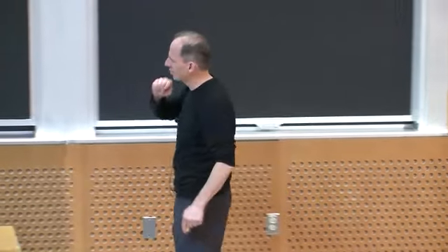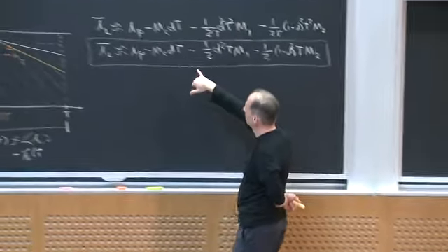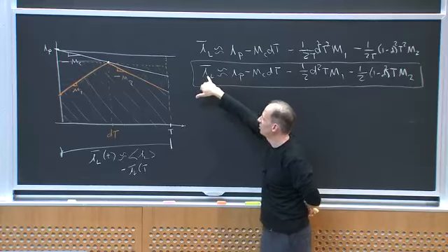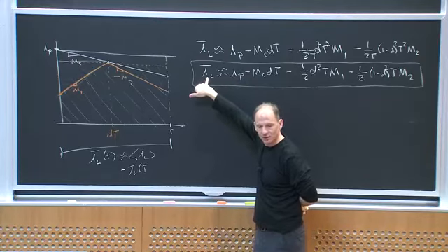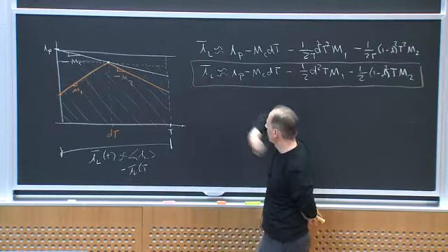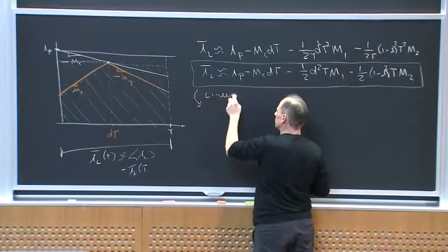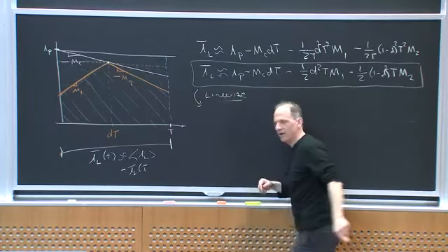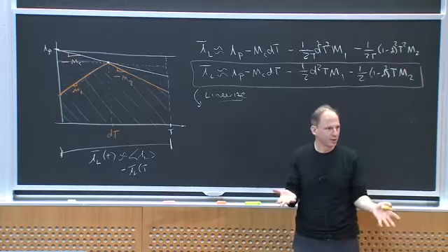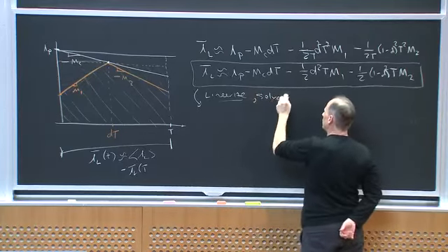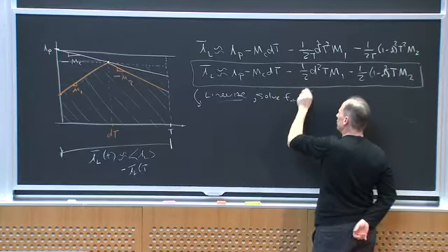So I've got a geometric approximation relating the duty ratio in the cycle, the peak current in the cycle, and the local average in the cycle. So let me linearize this, because we're going to substitute into our linearized equations, and I'm going to solve for d tilde.